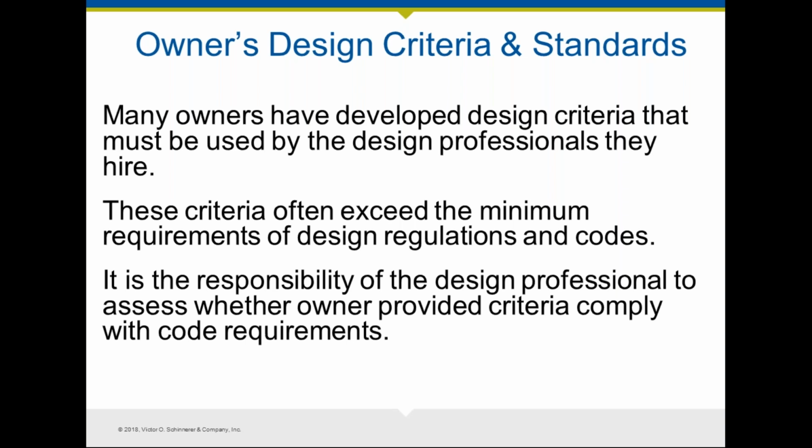You don't want to be in the midst of a design submittal later on to find out that the owner has different requirements, because that will require that you revise your design solution to accommodate the owner's needs. So insist on identifying what the owner's design criteria are, and make sure that your project managers know what it is and are planning on it accordingly.